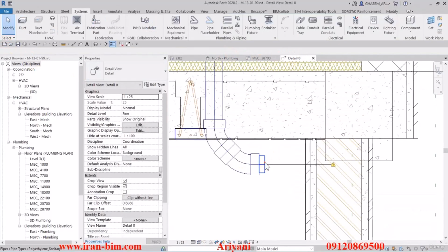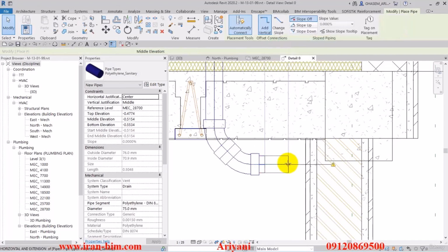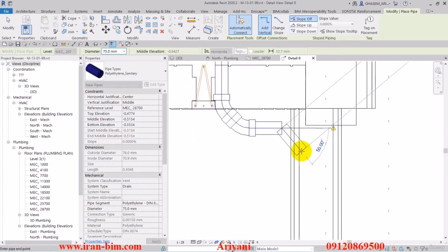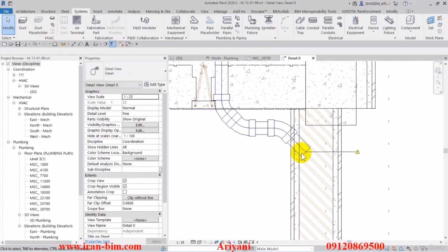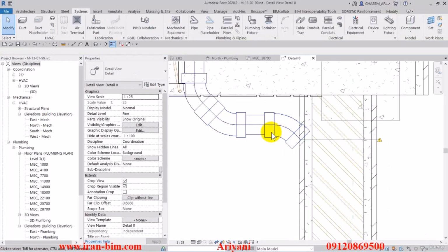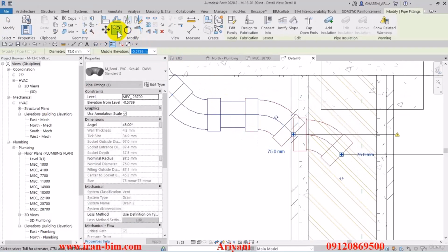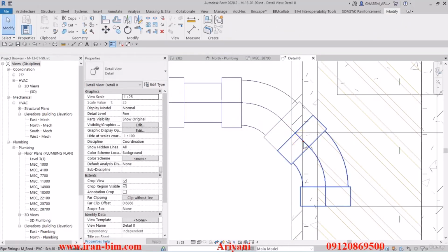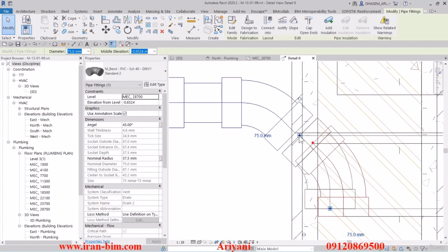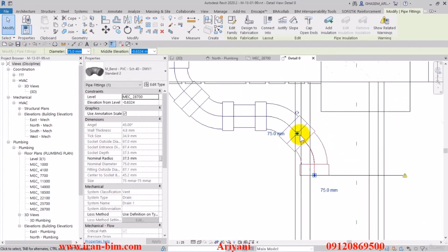So back to the plan, and here right click on this and select draw pipe, then draw it to this point right here, and then we go down using an angle of 45 degrees. Then I'll delete this extra bit that's been added because we need two 45-degree angles. So I can copy this rotating section again, then paste it right here and then align it using this line and then lock it right here. Let me just move it towards this direction a bit and then connect it once again until I can see the cross and the circle symbols because they actually symbolize the connection.